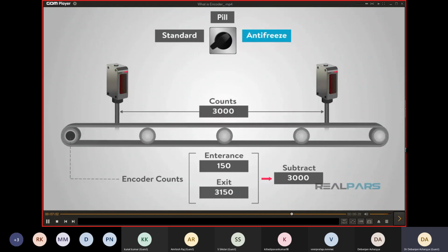You have also made the flexibility aspect of different types of bottles, as well as being able to place the entrance and exit sensors any reasonable distance apart. When back in run mode, the code knows that there's a handle to ignore when it comes into the process, and doesn't fault the machine.